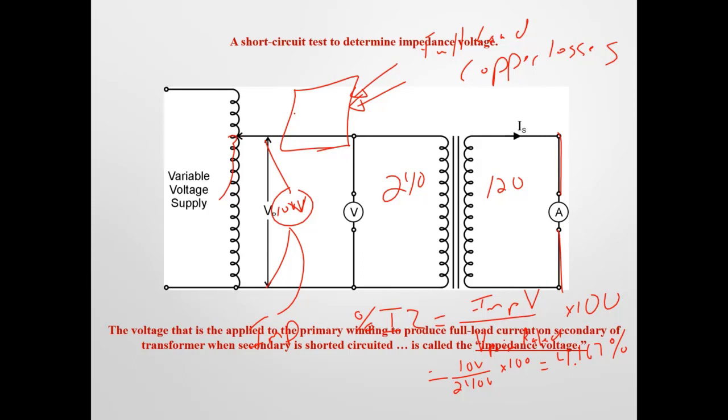I have to adjust that interrupting capacity based off of the transformer that's feeding that branch circuit. If I have a really high secondary short circuit current available, and I only put on a 10,000 amp, so 10 kA, interrupting capacity fuse, it might blow up if I have a really bad short circuit, or in a breaker, it could melt.